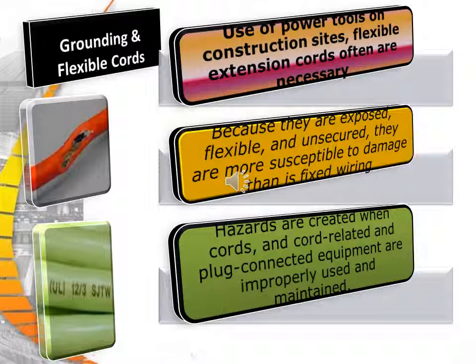Use of power tools on construction sites with flexible extension cords is often necessary. Because they are exposed, flexible, and unsecured, they are more susceptible to damage than fixed wiring. Hazards are created when the cords or cord- and plug-connected equipment are improperly used and maintained.